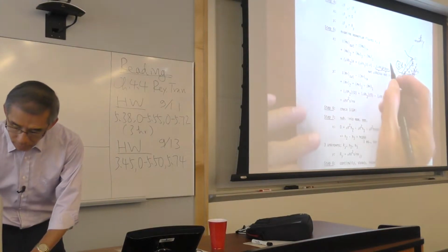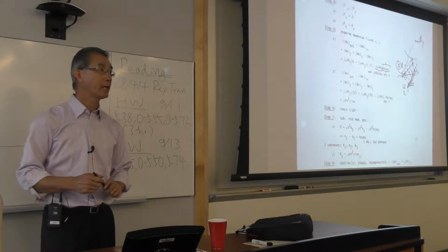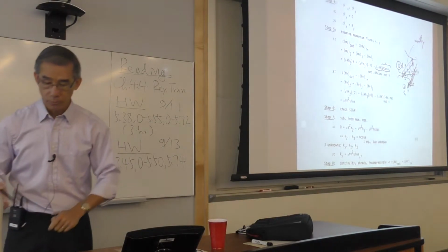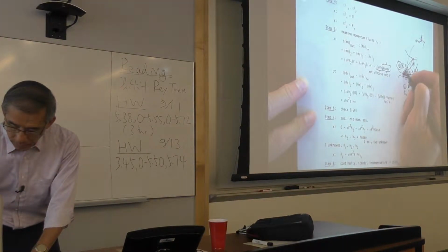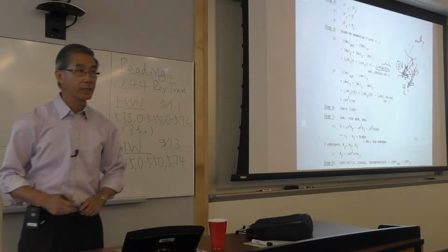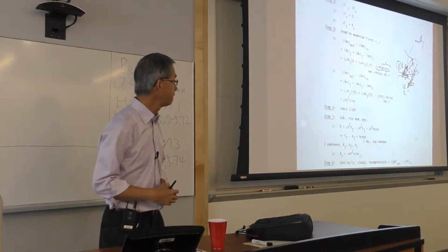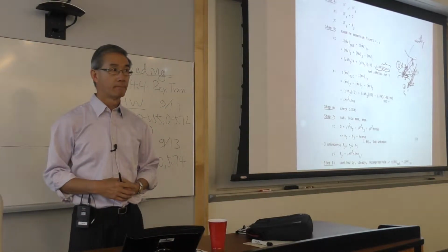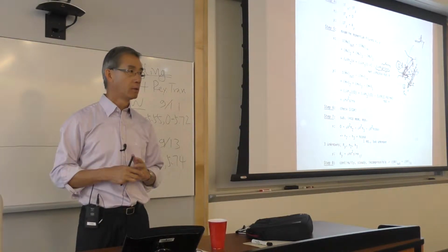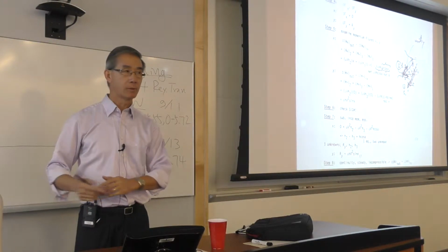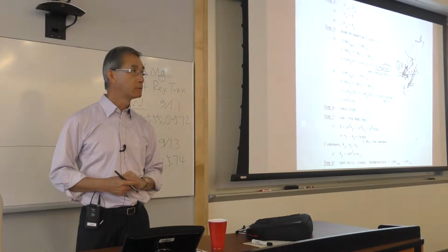Then continue on to the velocity at station 1, which is the component parallel to my x. So you have to use trigonometry to resolve the velocity here into the direction along the plate, which happens to be V cosine, with a plus sign. And that's it, you're done. The rest is bookkeeping. The physics is done. Any question?